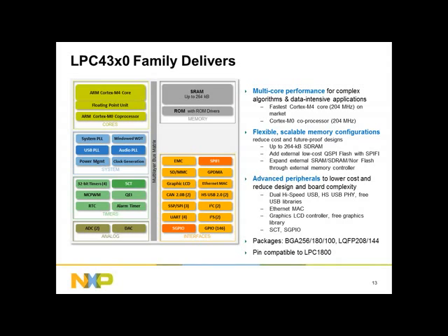Now, what about the other cores? Well, I really think of the other cores as coprocessors. What really is nice about the M0 in the top left is that you can use it for partitioning a lot of your I/O handling. Or, quite honestly, from our point of view, it's such a small thing for us to add. It's not easy to add it correctly, but a lot of our customers say, that's great, but I'll just use the M4 core and I don't need the M0. So don't think of this as something that you have to use the M0 core. Really, the M4 plus all the peripherals, I would say at least half the customers just like it for that, and the M0 coprocessor is future proofing of the device.